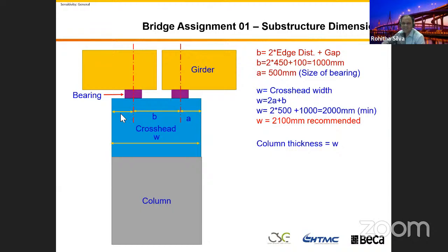This distance in standard practice is 500 mm or 550. It depends on the size of your bearing. Some people push this one really hard to 450, 400, but sometimes it's really hard when you come to design, especially they neglect the reinforcement stirrup here. When you bend the stirrup, you get a 4 times diameter radius in here. They neglect that one. Because of that, in some bridges you get a crack in the concrete in here. Yeah, so you can't see this stuff.